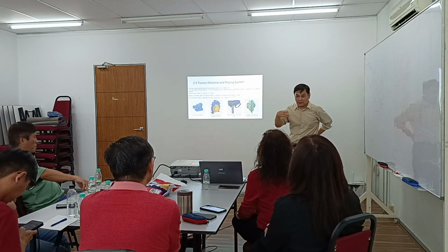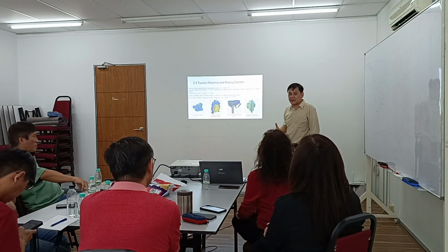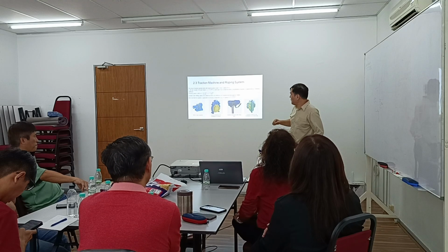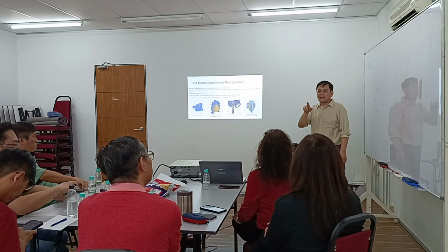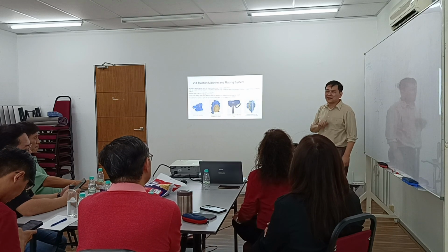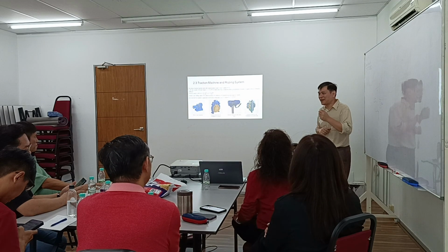But in the market then the inverter sizing usually we do one size higher. That means 7.5 kilowatt motor, the inverter sizing will be 11 kilowatt. Any reason why? Margin, correct?